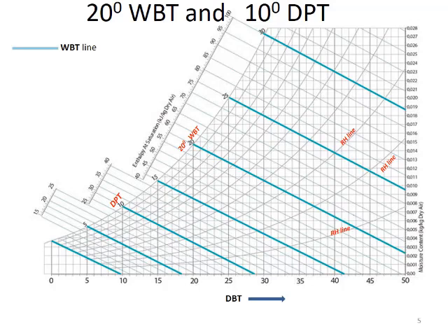So in order to mark 20 degree WBT, first locate 20 degree DBT point on the DBT axis, then go up like this till it intersects the saturation line. So I have written there 20 degree WBT, right? Now from that point you have to move along the constant WBT line. Now since you don't know where to stop, just keep that line in your mind, okay?